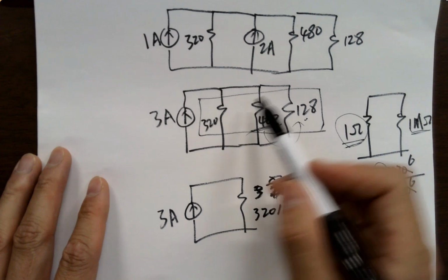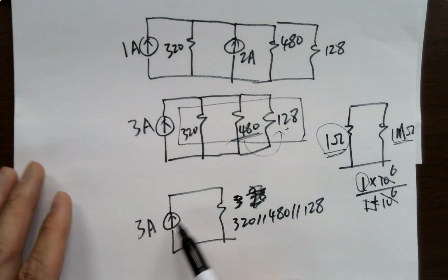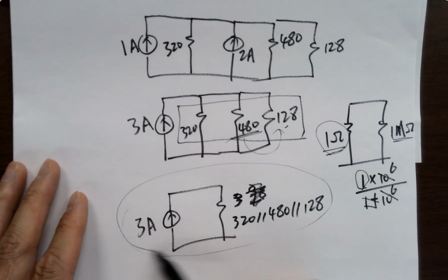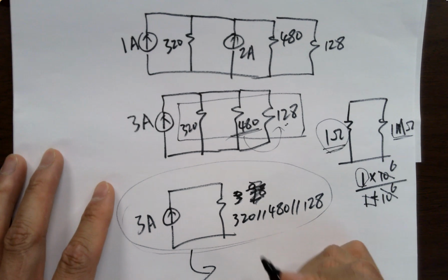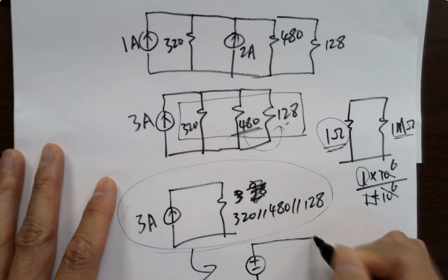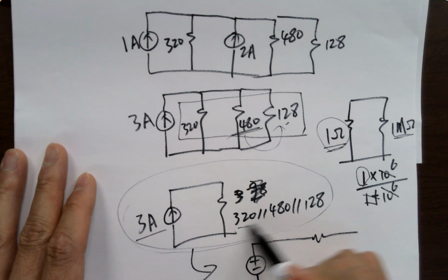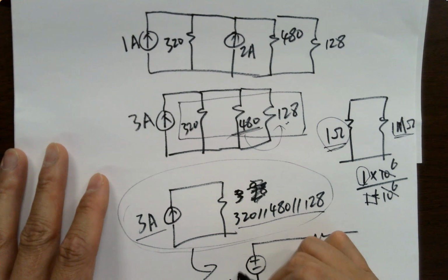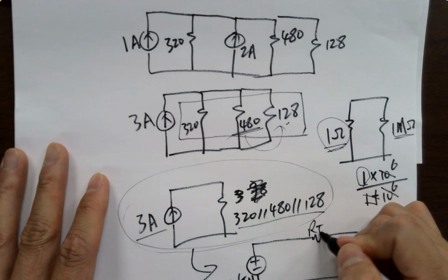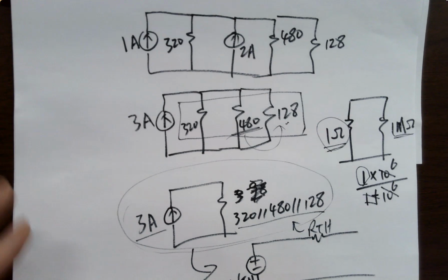But anyway, eventually you convert these 3 resistors into one, so you are getting an equivalent circuit like this. And you can also convert it to its Thevenin equivalent circuit by doing a multiplication, right? So this will be 3 amps times this, and RTH is not changing. RTH is exactly the same resistance as this one. Same resistance. Any questions so far on this? No?